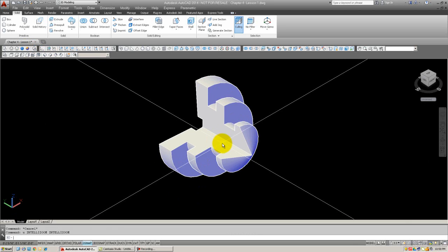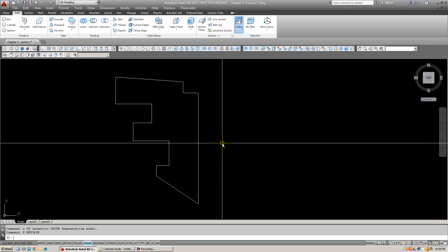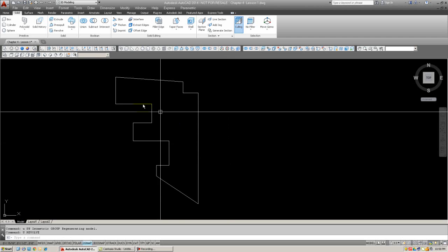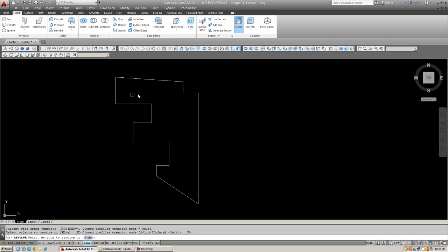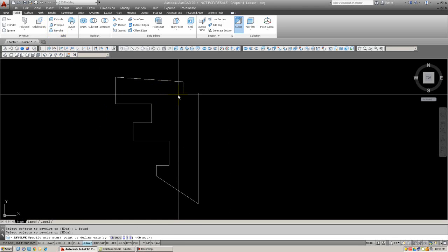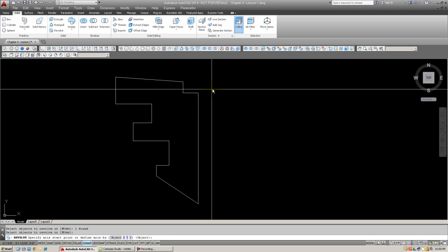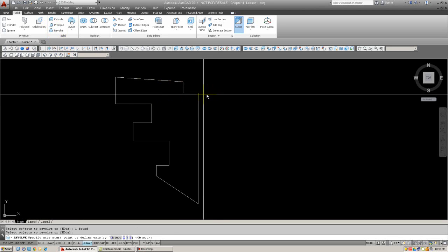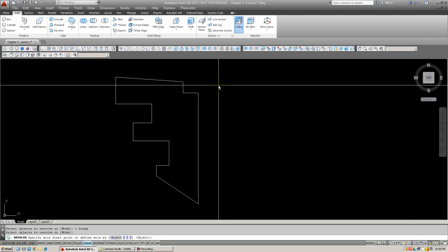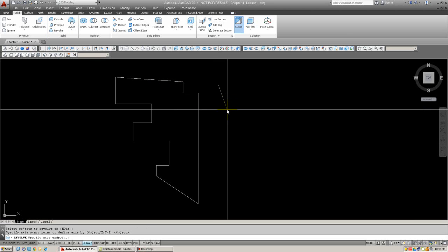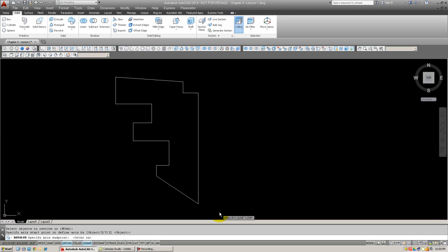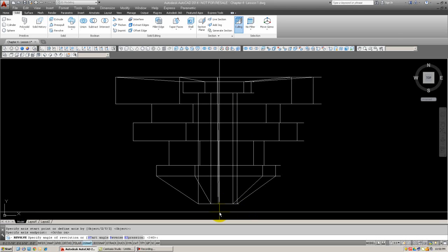Now here's another variation I want to do for you. Go back to the shape, I'm just undoing. I'm going to do revolve again, this time using a ribbon. Select the shape. Now I'm going to put the axis of revolution not on the object but some distance away from the object, and note the distance I'm using, some random amount, but take note of it. So I'm going to click here and using ortho, here's the other click, and let me also use 270 degrees,